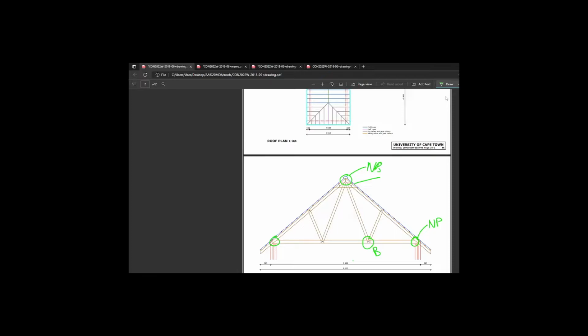Whilst we're here, let's go over the bolts. So I've just said in the absence of any indication, we assume it's a nail plate. In the presence of dots, it is a bolt. I say a bolt very specifically because it's not the bolt. There are types of bolts, M16 and M10, and that pertains to the thickness of the timber it has to travel through, right? So 100 mils plus is an M16. Now I don't mean the weapon. And an M10, we will just assume it's less than 100 mils. This is because I'm being a bit lazy and not looking at the table.